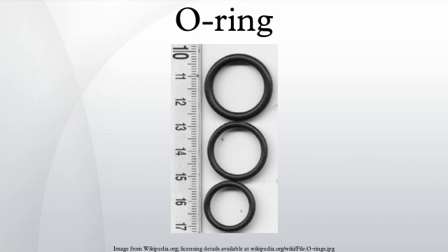Nitrile rubber is a common material for O-rings because of its good mechanical properties, its resistance to lubricants and greases, and its relatively low cost. The physical and chemical resistance properties of NBR materials are determined by the acrylonitrile content of the base polymer. Low content ensures good flexibility at low temperatures, but offers limited resistance to oils and fuels. As the ACN content increases, the low temperature flexibility reduces and the resistance to oils and fuels improves.